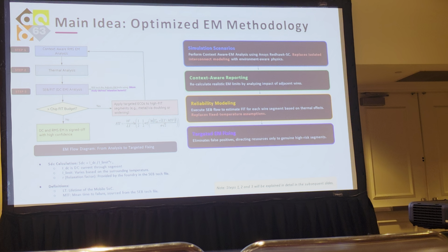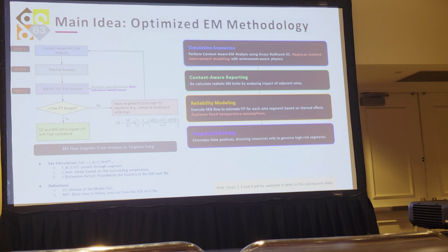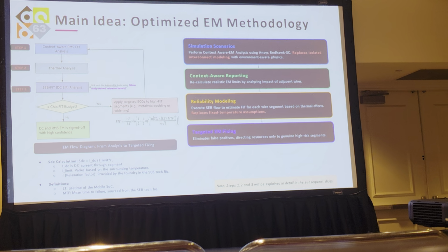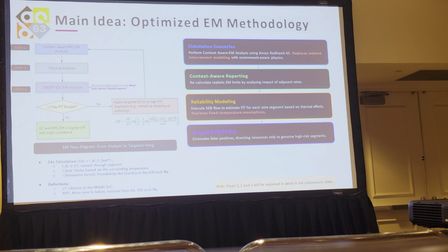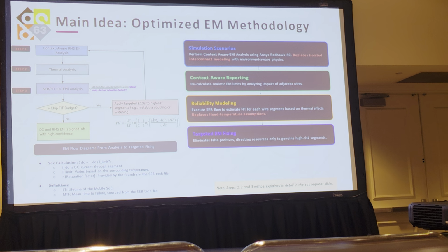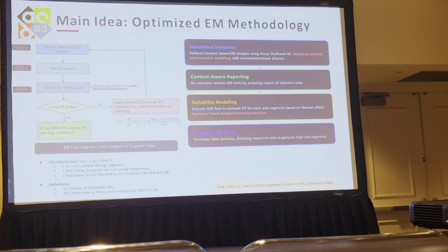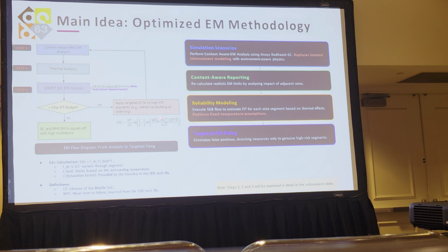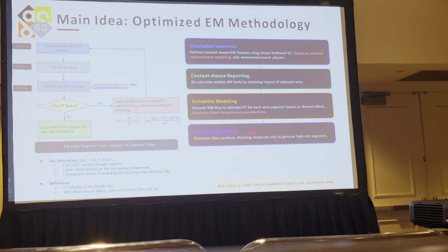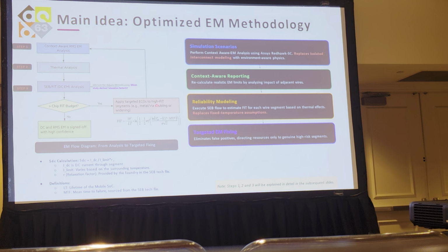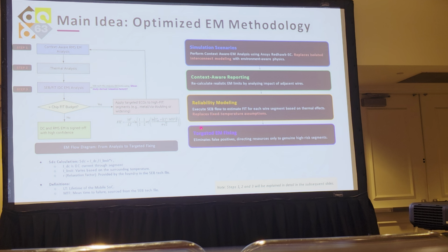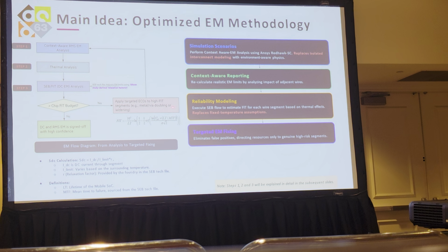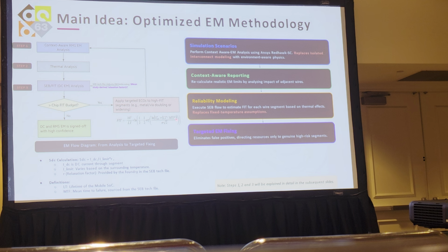As we see in this equation, this is the FIT equation. Basically, the tool calculates the FIT of a particular segment, which is nothing but the failure in time. The temperature calculated in the thermal analysis is taken as an input, and using Black's equation, the tool recomputes the mean time to failure based on that temperature and substitutes it in this equation.